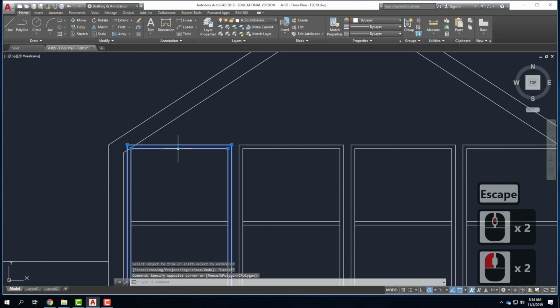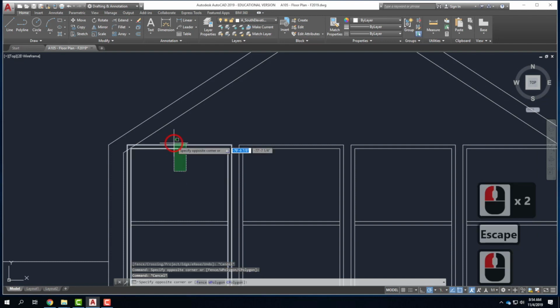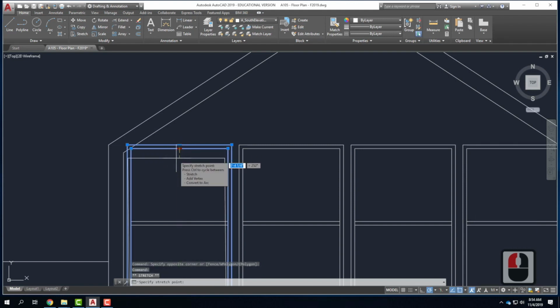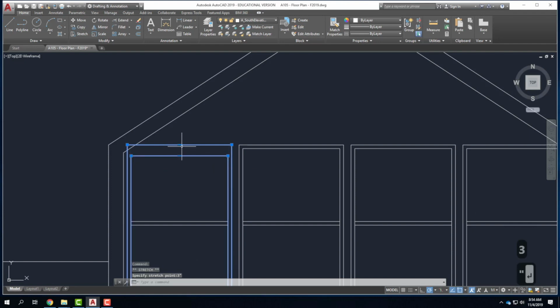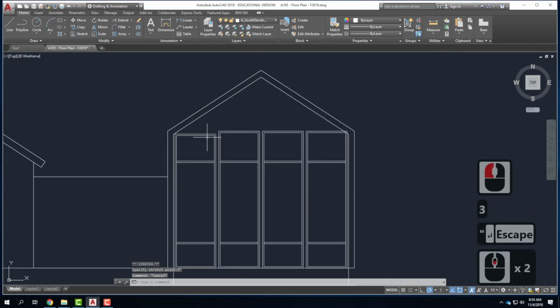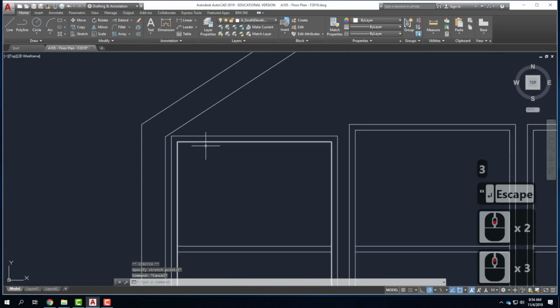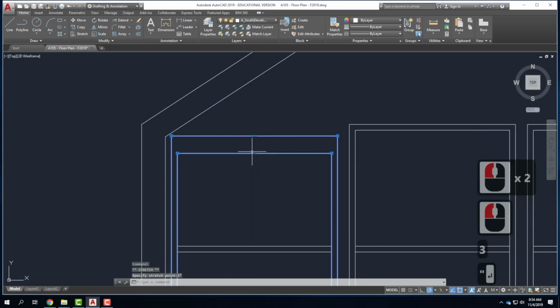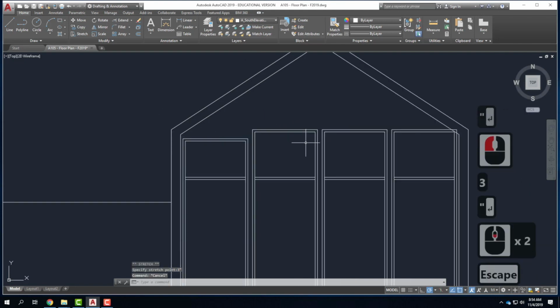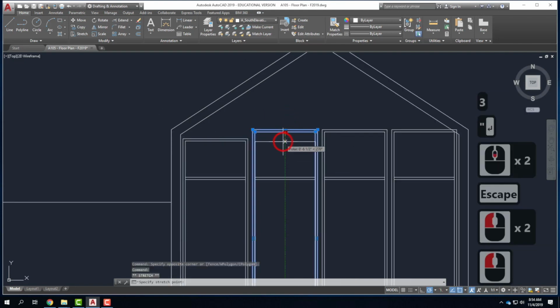And these ended up being a little bit too tall. So I'll take these and I'll move them each down. I'm going to select them and then pick this line in the middle, which is the stretch point. And then I'll specify how far I want that stretch point to move straight down. So we'll go down by 3 inches for each one. That puts them underneath that window. Actually, let's do a little bit more. There we go. So I can do this for each of them.